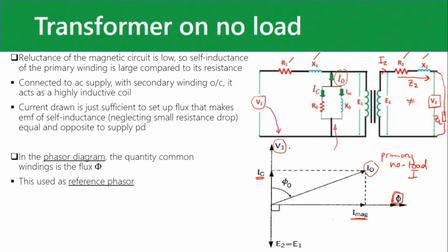So this is your applied voltage. All right, and you remember the back EMFs, which were in opposition to the V1. See E1 and E2 there. The back EMFs over here are 180 degrees in opposition. They oppose the current.